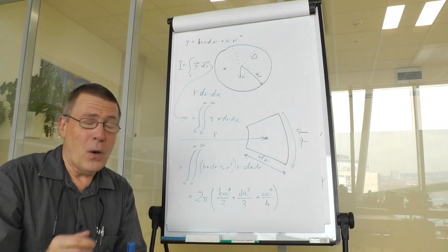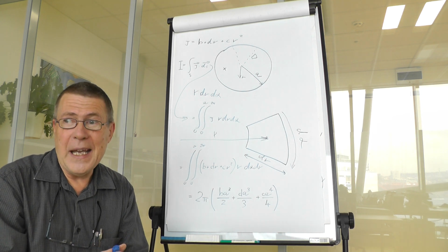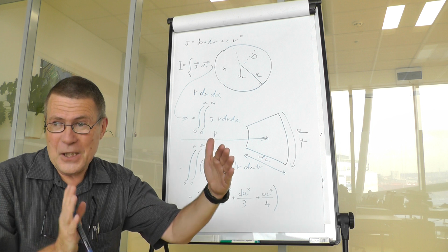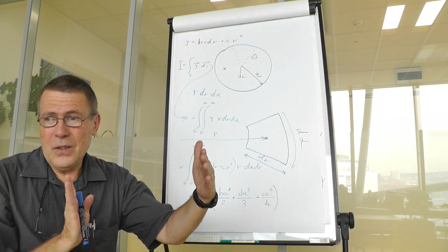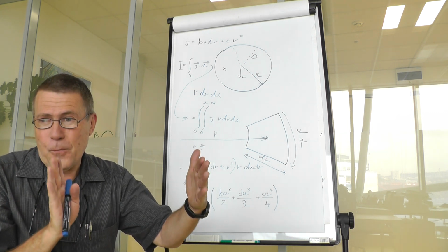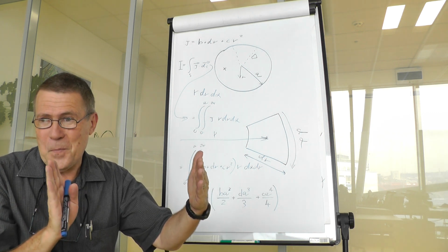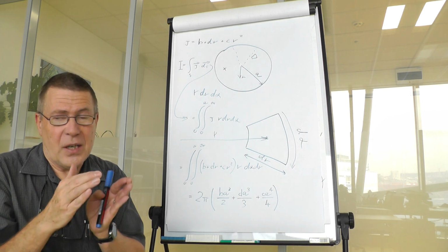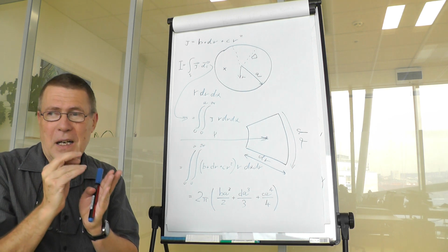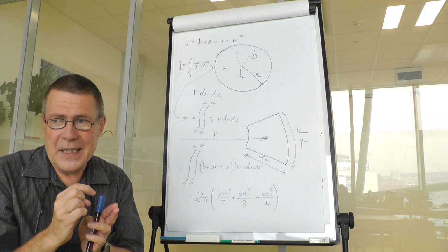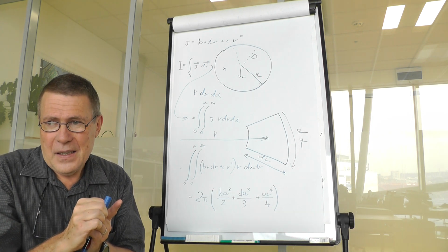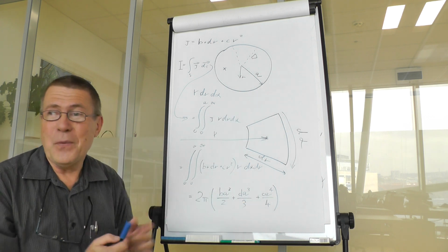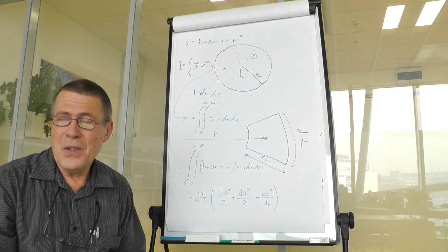But for some low frequency or DC cases, we can have magnetic flux also inside conductors. And therefore, for the same set of conductors, let's say a coaxial cable, there would be at least two values of inductance, one for high frequency, the other for DC. And the difference between those two inductances is called internal inductance. That's the inductance of a conductor that is resulting from a magnetic flux flowing inside the conductor. To be able to establish it, we will need a calculation like this, and we will need it 1 week later. That is next Tuesday.